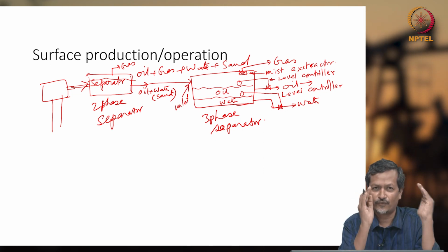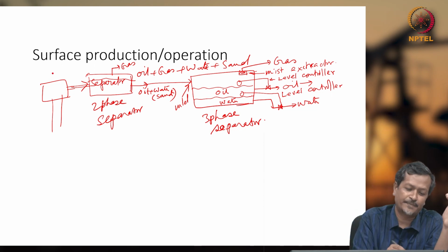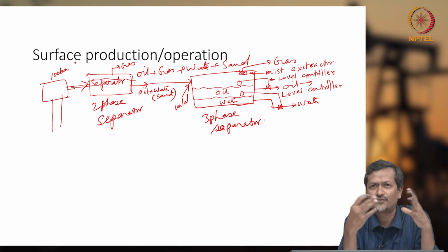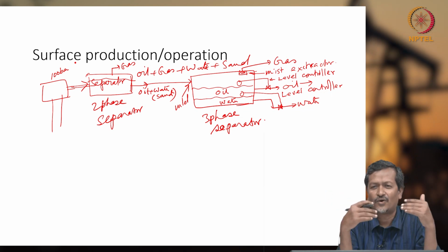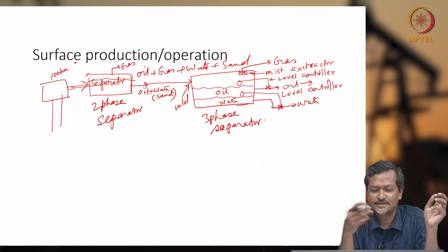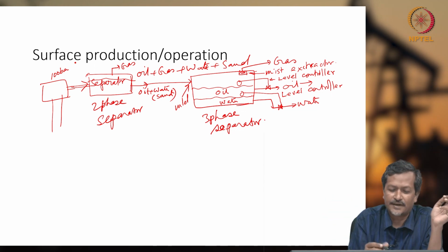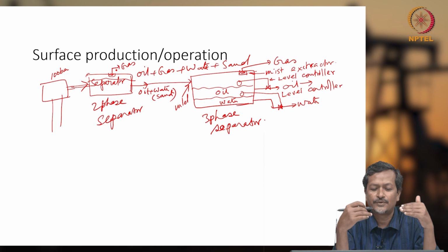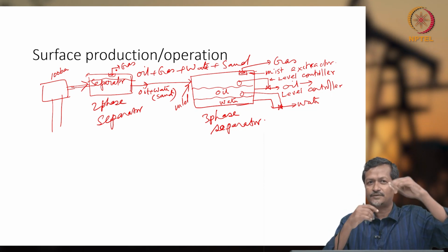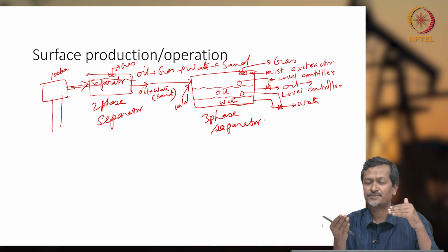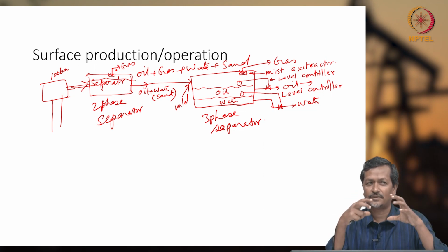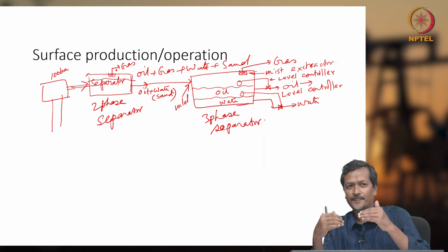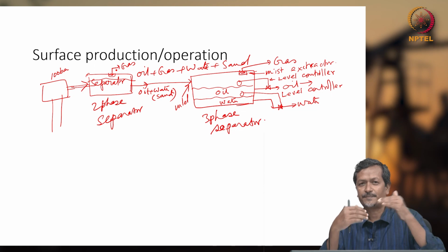So, from the wellbore, you are getting very high pressure fluid, let us say 100 bar, for example. Then in the first stage, you do two-phase separation. You remove all the free gases or dissolved light gases, and condensate if possible, as much as possible. There will also be one mist extractor, so that liquid should not go into the gas line. Once you separate gas and liquid, there will be some pressure drop. If you are not reducing pressure, then the two phases will be a mixed phase, so separation will be difficult. So at each stage you reduce pressure, and then you separate oil and gas.